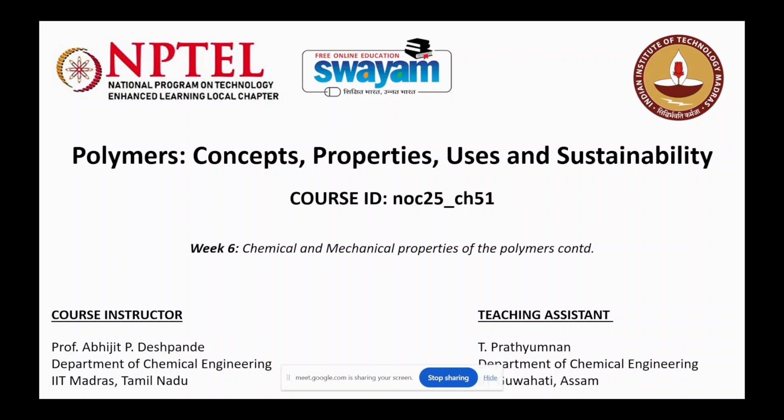Similarly, for different types of composites that we make, the filler, the reinforcement, and the matrix will have different design requirements or property requirements. Apart from mechanical property enhancement, composite formulation could also be done to increase the electrical conductivity, specifically in the case of storing energy or improving the electrical properties of polymers. As we discussed, even though conducting polymers have a higher electrical conductivity compared to other insulating polymers, in the undoped state they still behave more like a semiconducting or an insulating material. So in order to boost their electrical conductivity, we go for composite formulation, where we typically add nanofillers so that their electrical conductivity can be enhanced.